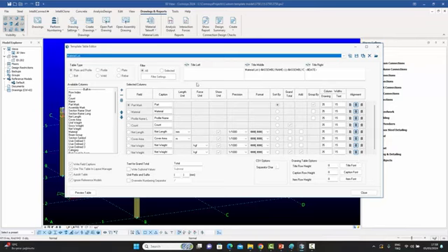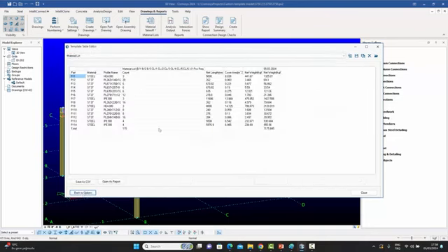And now you can basically, like I said, use this in the layout manager. But I'm going to just show you how to preview this. Whatever you've done, you might want to preview what kind of results it's giving. So just press the preview table, and it'll show you a text preview of the table, which is obviously not exactly formatted the way it will appear on the drawing, but it's a quick preview to give you an idea of what kind of table it's producing.